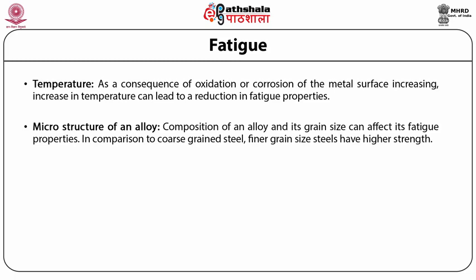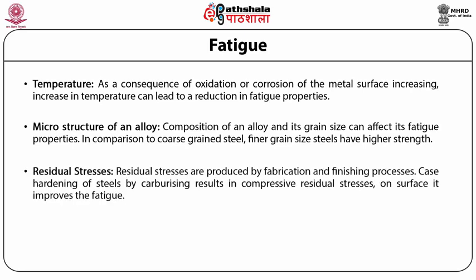The next factor which affects fatigue is residual stresses. Residual stresses are produced by fabrication and finishing processes. Case hardening of steels by carburising results in compressive residual stresses on the surface, and it improves the fatigue properties.